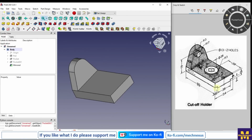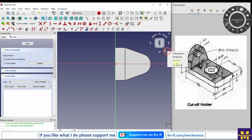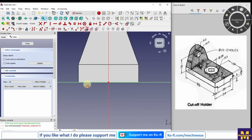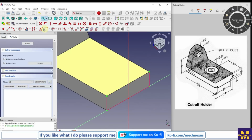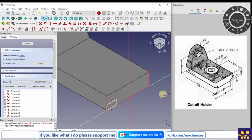Now we will make these two cuts here. One is here and one is here. For this I will select this face and say sketch. I will go for the isometric and then go for the right plane. Now I will project these two edges, this one and this one also. Now I simply draw two rectangles, one here and one here. Now we will give the dimensions.